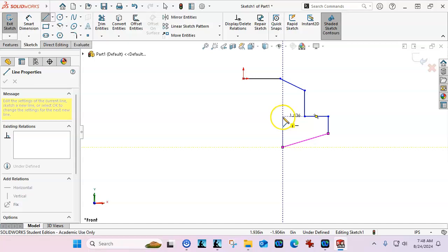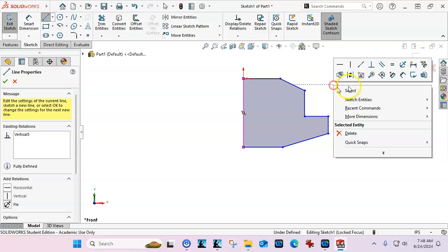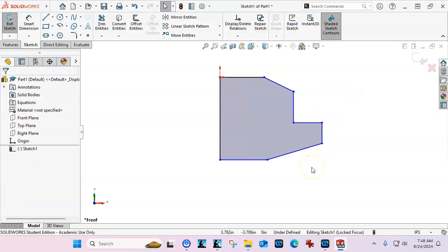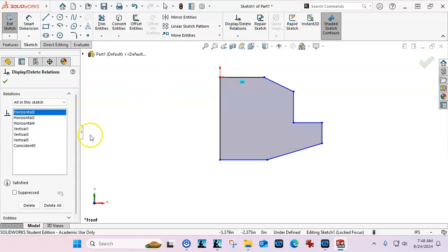And then we can pull the inferences back to horizontal, and I'm looking for the vertical. So a lot of visual clues going on the screen that you need to learn to read and make it kind of a second thought, or when SolidWorks helps you by automatically applying one of those inferences, that you know how to correct for what you're doing.